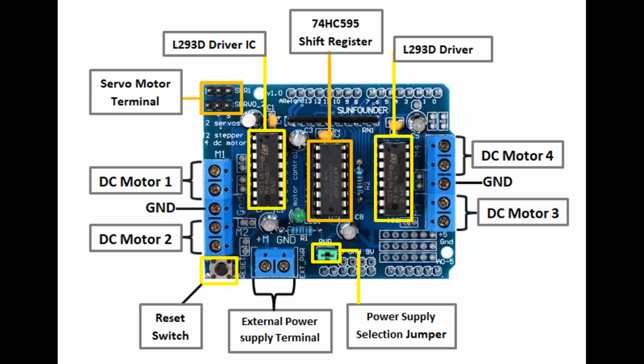Speed control. By varying the frequency of the AC power supplied to the motor, VFDs can control the motor's speed. The motor's speed is directly proportional to the frequency of the input signal. This allows for efficient speed regulation, which is crucial in processes requiring variable speeds.